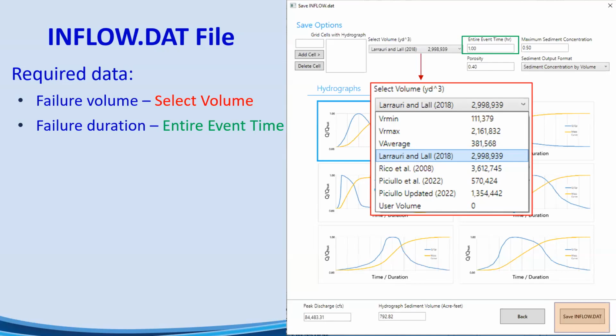You don't want that very large volume to enter as a boundary condition into one single cell in FLO-2D. So you may want to divide this hydrograph between 10 cells, 5 cells, a number of cells, to enter the flow into the FLO-2D domain. So if that is what you want, you need to add the different cells here.